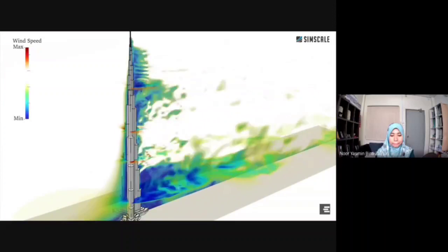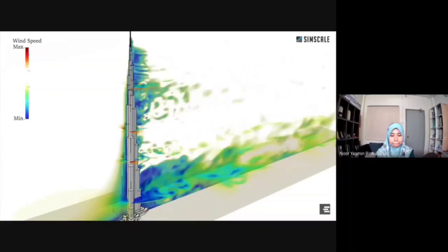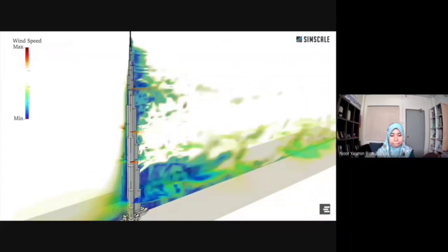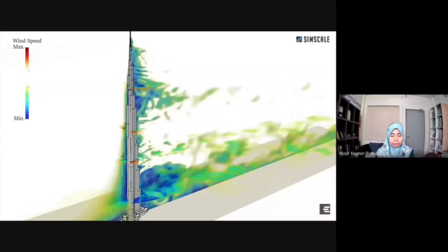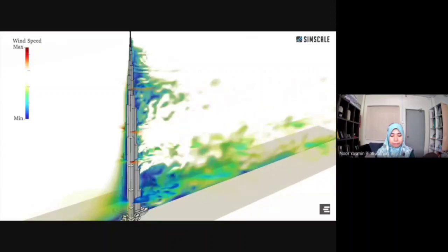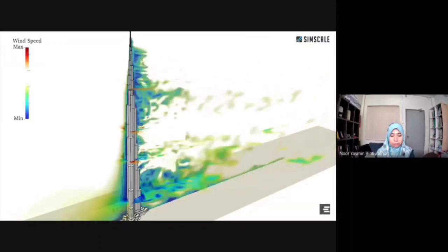At mid-height, the cross-sectional area not only decreases, but also changes between symmetric and non-symmetric form. In this animation, a non-symmetric section is highlighted that shows non-coherent vortex shedding. This helps to spread out the frequencies along the height and avoid a single dominant oscillation.